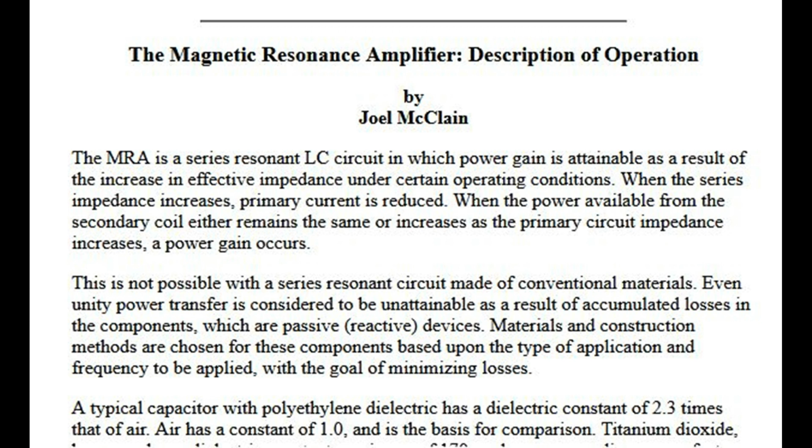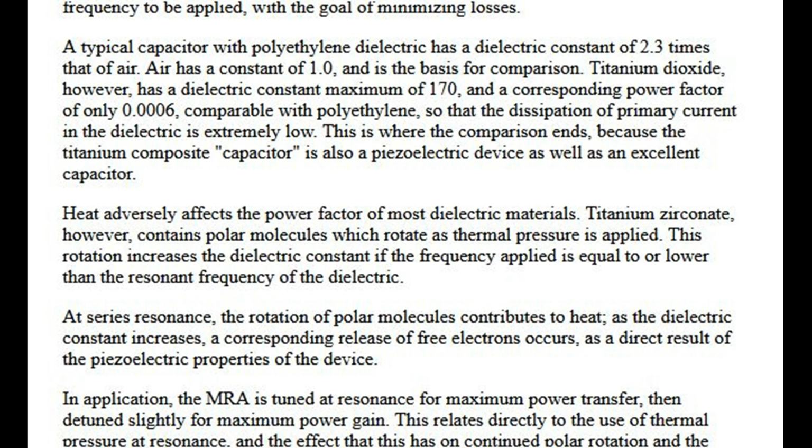Titanium dioxide, however, has a dielectric constant maximum of 170, and a corresponding power factor of only 0.0006, comparable with polyethylene, so that the dissipation of primary current in the dielectric is extremely low. This is where the comparison ends, because the titanium composite capacitor is also a piezoelectric device as well as an excellent capacitor. Heat adversely affects the power factor of most dielectric materials.